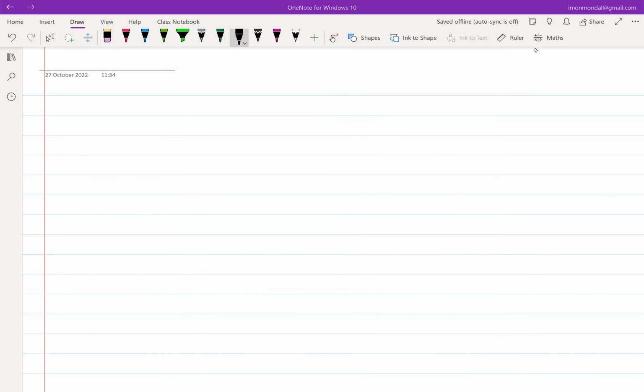When we stopped at the end of the last class, we were discussing the role of an inverter to give you amplification, right? So the chain of thought was we would like to replace the resistor in a common source amplifier with an active device. When you replace it with an active device, you have to make sure that, looking into the same terminal, you get a drain, not a source, which means you cannot have an NMOS. You need a complementary device, which, as it turns out, is a PMOS that we are familiar with.